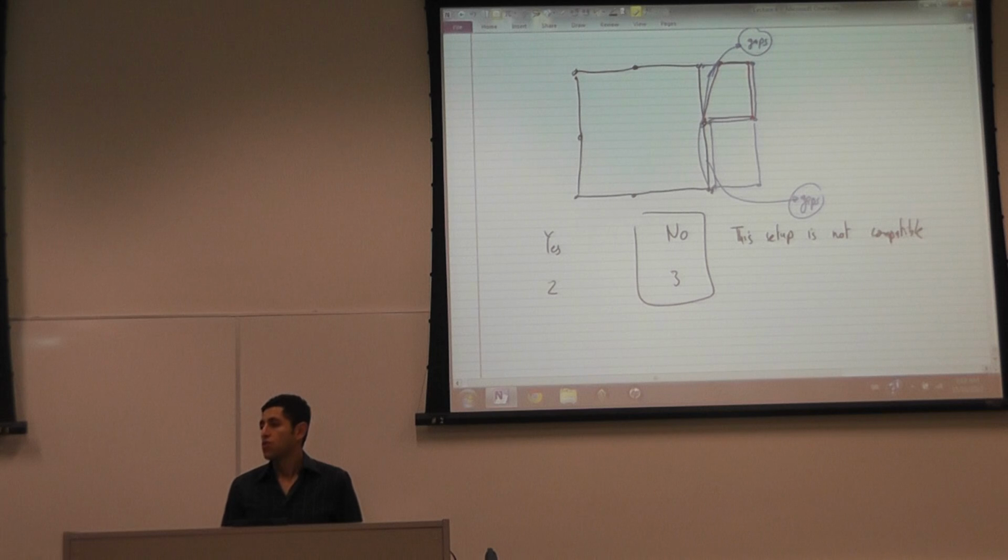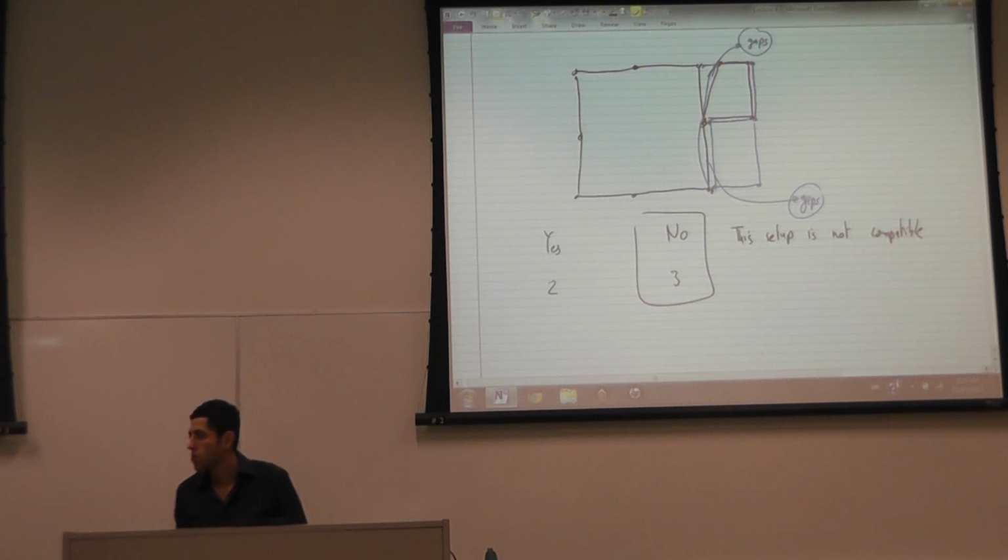Now, of course it's up to you. This is all approximation. If you model something like this, you just need to be aware that the mesh will look fine. You're not going to see curved lines. But you need to realize that these are incompatible elements, and this is an incompatible configuration. And there are incompatible elements that are used for specific applications. If you look at the types of elements in Abaqus, you're going to find incompatible elements. I've never used them, but there are people who use them for specific applications. They need this incompatibility for some reason.